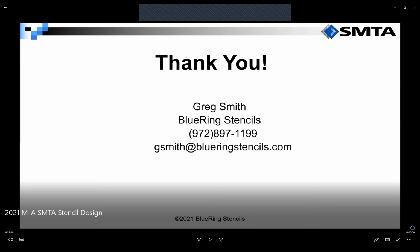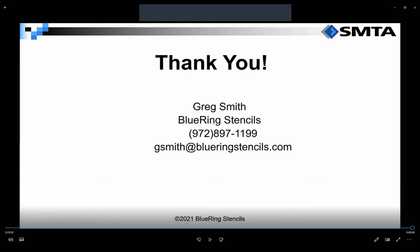Then if you take that and rotate it 180 degrees so that you take away material from the outside of the component, that would be an application for addressing tombstones. With tombstones, you want to remove metal from the outside edge of the component, and with solder balls, you want to remove solder paste from the inside center of the component. So really, one is just a rotated 180 degree version of the other.